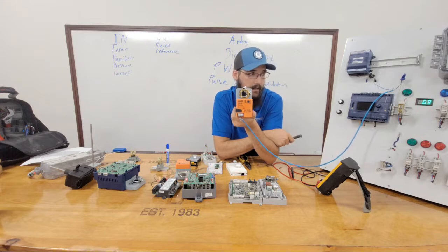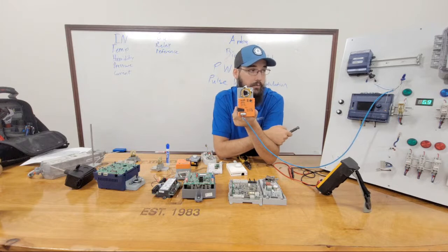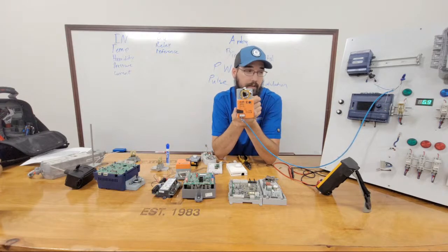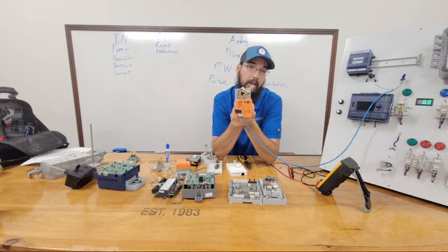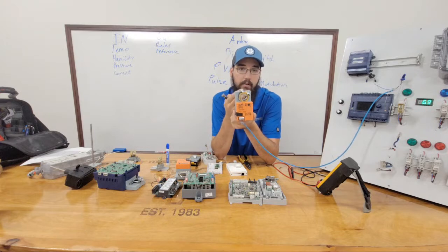Now you've got to put it back, right? It's not going to reset itself. You've got to be the one to set it back where it needs to go. But that is one really quick, easy way of testing. Well, one, is the actuator getting power, right? If it's not getting proper 24 volts to begin with, it's not going to function.